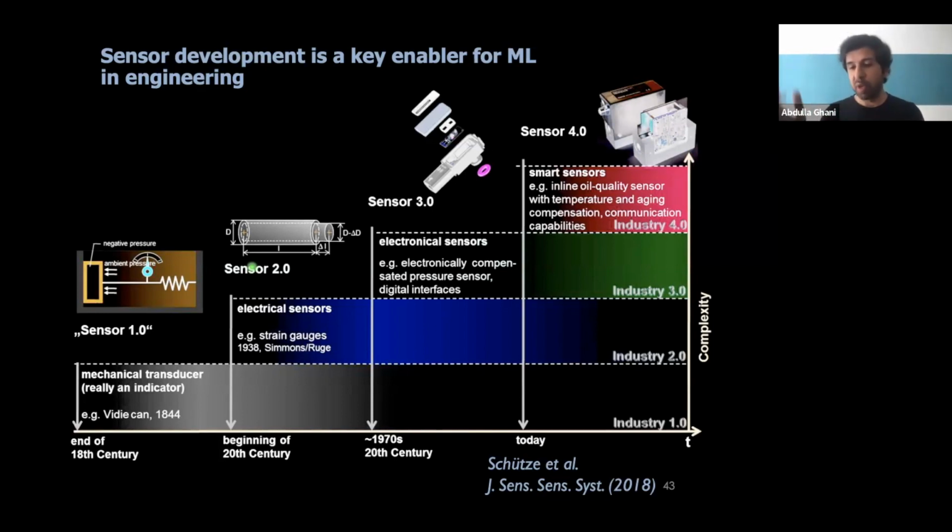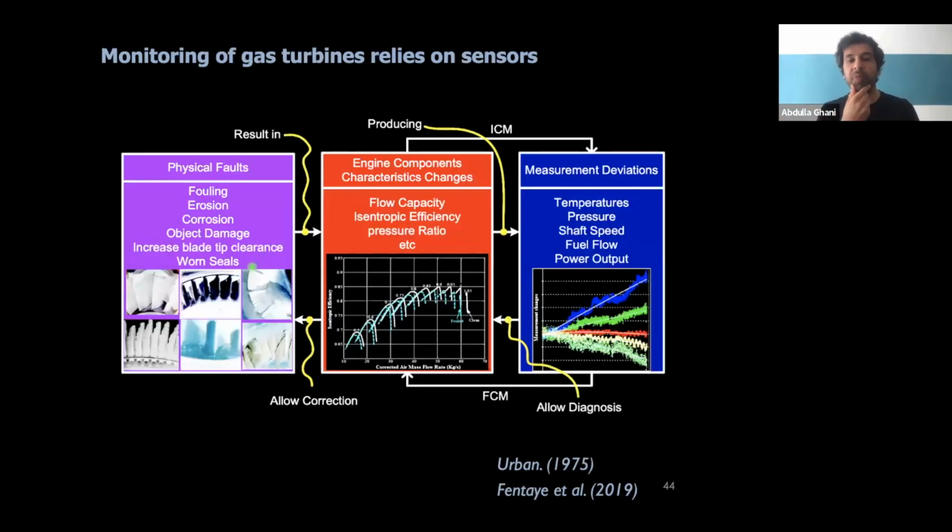In our field of combustion, and in particular I'm talking about gas turbines, sensors are always used. From Werner Krebs, for example, I know that in a Siemens gas turbine there are around 6,000 sensors. Of course, there are not 6,000 pressure sensors, but at least you have some of them. These are used to track the health of your engine over time. You see with time that some pressure signals or temperature profiles deviate from the means they had beforehand, and then you can indicate which maintenance procedure to take, to do an overhaul or something.